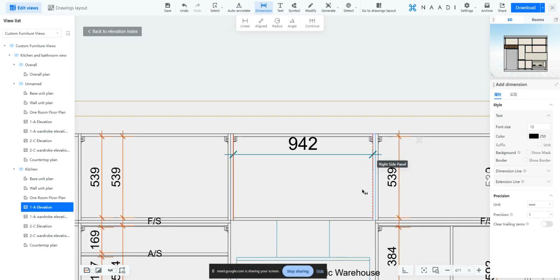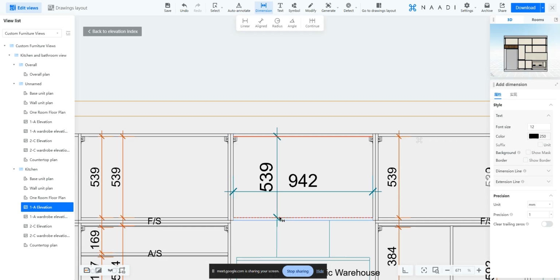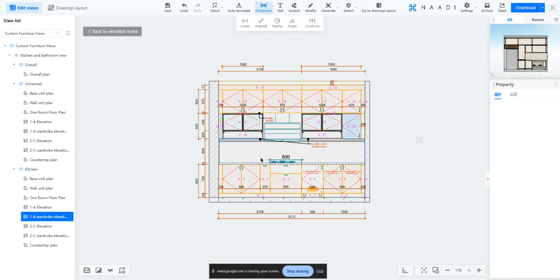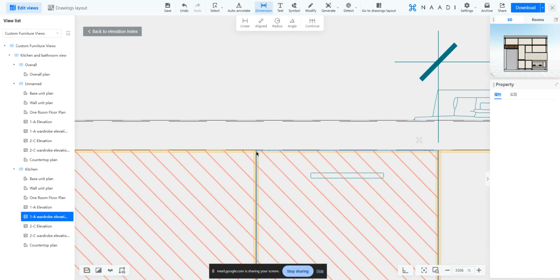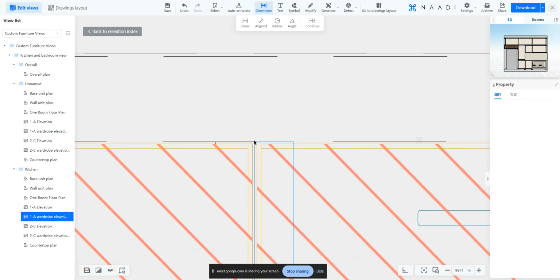For this you don't even need to zoom in if you want to add any missed dimension here, because it is plain. You can directly add it. Same thing for the verticals too. If you want to add a vertical, you just do it from the plane point of view and get it done. But for the external elevation alone, for now, please zoom in and click on that black intersection, because those black intersections represent the carcass meeting point.